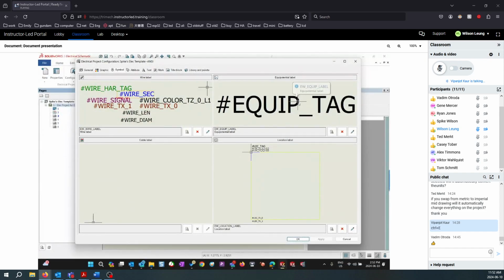If you right click on it, there are two types of numbering of wires we would do in lesson 6 tomorrow afternoon or morning. If I do equipotential type of numbering, any equal potential wires will have the same wire number.